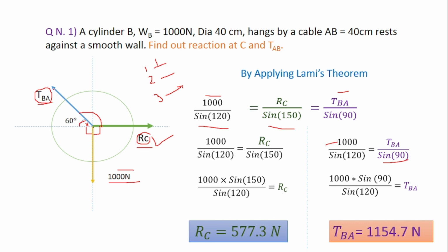To draw the tension in any cable, we break that cable and show the tension force there, and it acts away from the center. So if you follow these basic rules, then you can easily solve sphere related problems, and there is always one question based on the sphere, either for 4 marks or 8 marks, to find the support reactions.